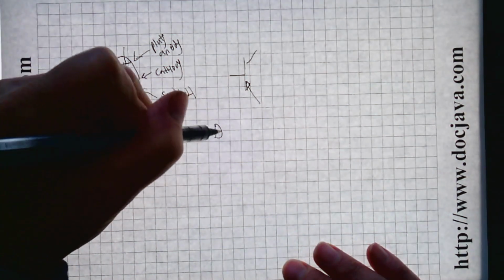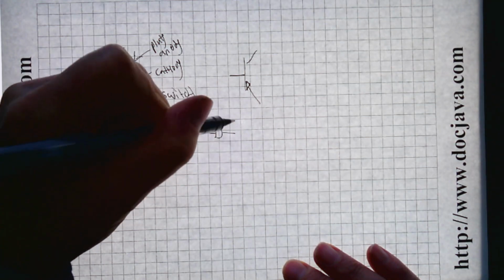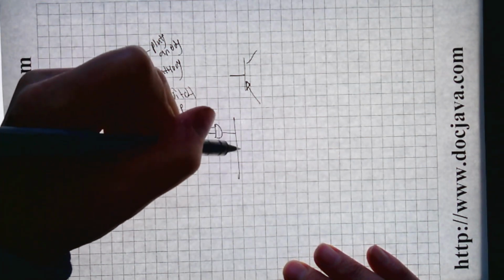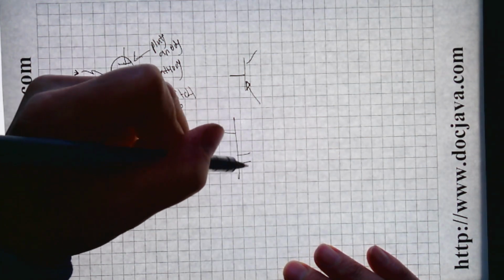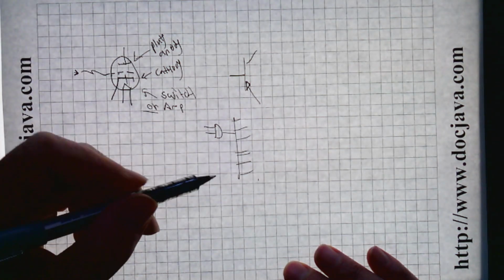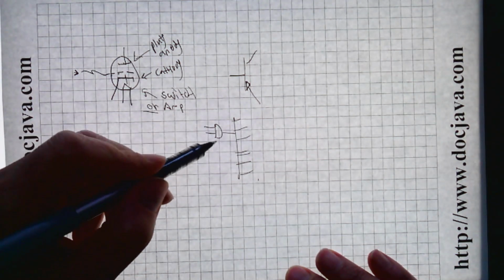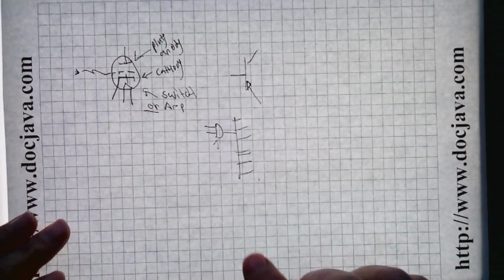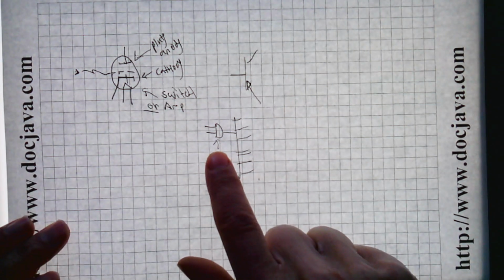And that's what happens when you have too much fan out in your TTL. If your TTL is designed to drive only 10 inputs, and you try and drive more than 10, like a little bus with lots of tapping on the bus, then that's going to essentially cause the transistors in the gate to act in funny, nonlinear ways.